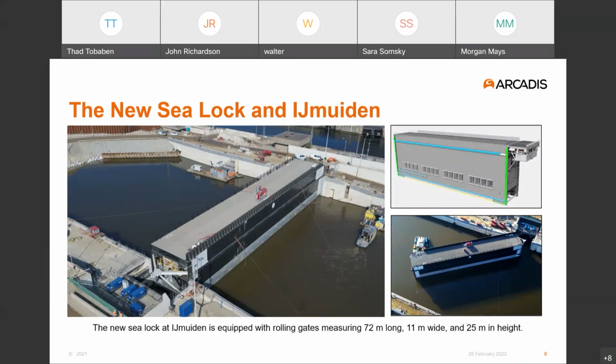I should comment that the doors are symmetric in design, and so on the side of the door you can't see in the figure, it would visually look to be the same. Braking bars are positioned at the openings, and then the sluice gates themselves that control the flow of water and the leveling of the lock are located in the center of the doorway. The figure or photograph at the lower right shows one of the doors being put into place.